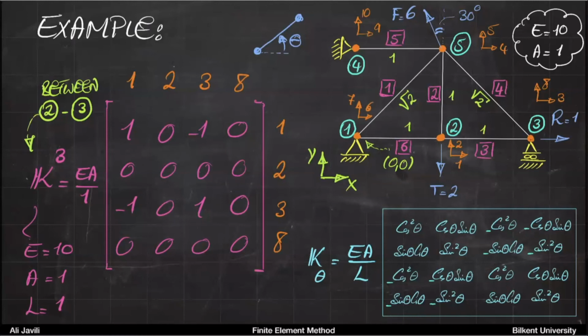Okay. But it turns out that it doesn't change the result. So you just pay attention to that: the node numbering is arbitrary as long as you are careful with the way that you assign the angles. So if you say it is from 2 to 3, then you assume theta is 0. If you said it is from 3 to 2, then theta would be 180. The same thing with 45 degrees or minus 135 or something.